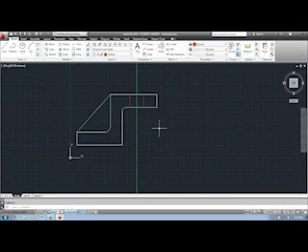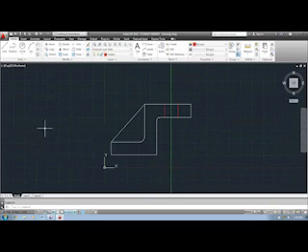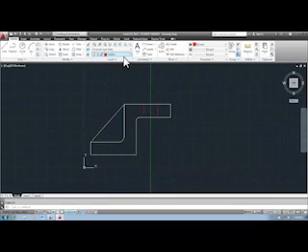To completely describe this part, I would need the view that I have here, which I defined as the front. However, technically it's, I guess, more of a side view. Then I'm going to make a top view and a left view. In order to do that, I'm going to have my construction layer. And I'm basically going to work on the top first.